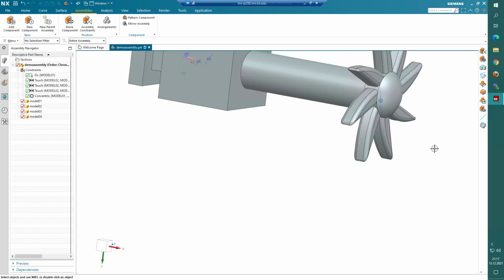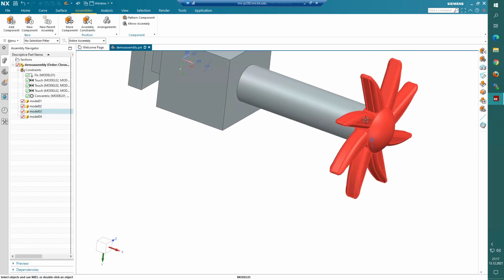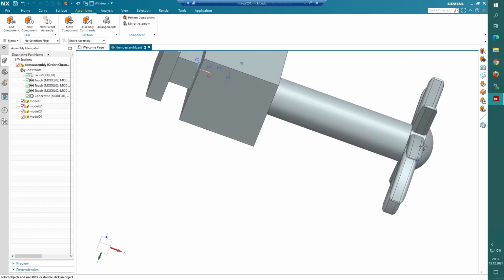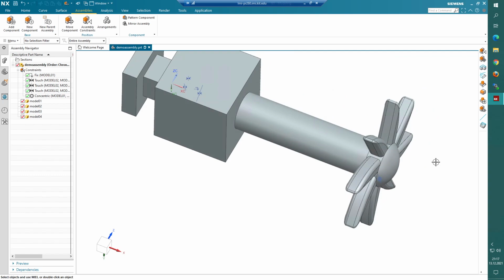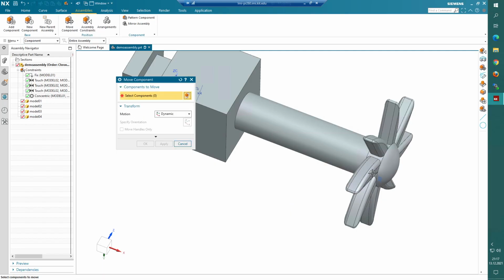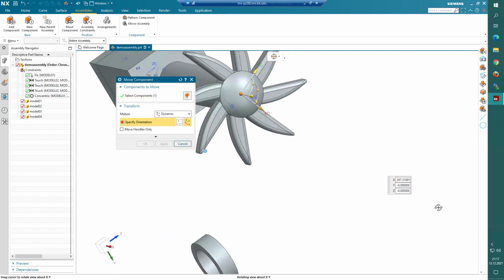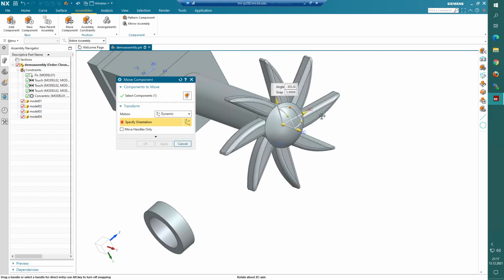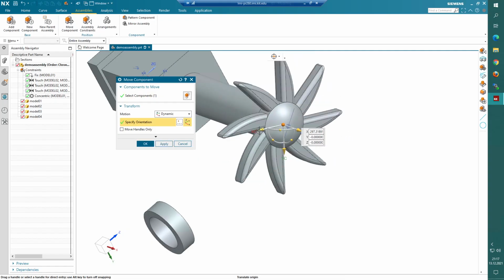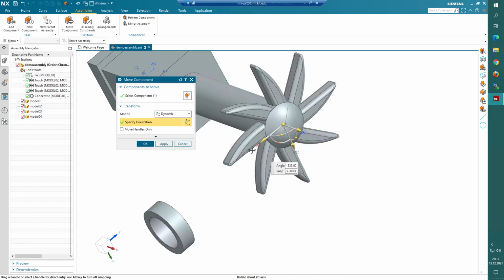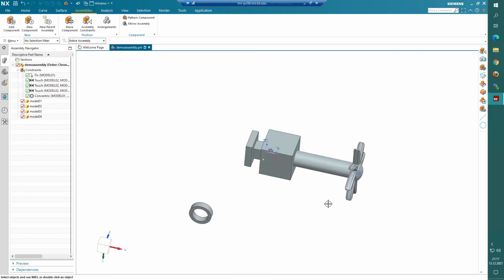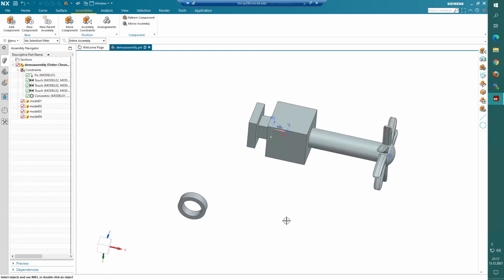And now we have this constraint, which lays the center point on this center point, and the two planes on each other. And that already constrains everything that we need. And the important thing is that we can still turn this around the axis, but don't move it in any other direction. And also don't turn it right here, yeah? So we can only turn it around this, on top of this other circle, so to say. Okay? So that's one of the two.